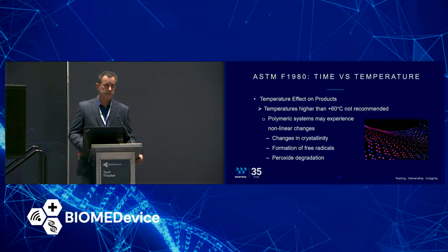So now let's dig into ASTM F1980 just a little bit, talking about time versus temperature. Now, for the accelerated aging, that's the whole premise, is that we're going to increase the temperature to shorten the duration of time that we're going to age these products. And we'll see that it's going to be very significant.